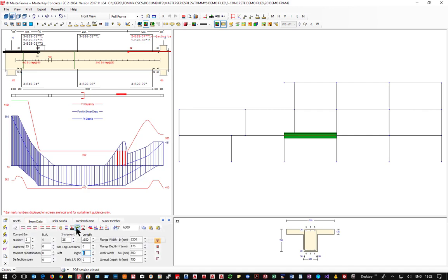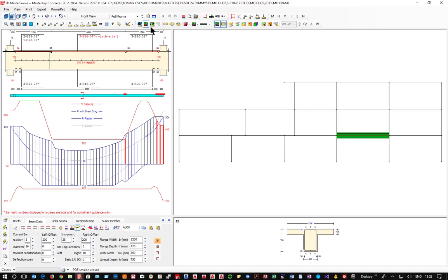So I use the lasso to stretch both of these out past that point, and therefore it now solves the problem. Again, remember we're in Eurocode, so when we move things it does change it slightly more than you would have thought. So moving along, we'll see that the next span we do need to maybe go up to 16s.